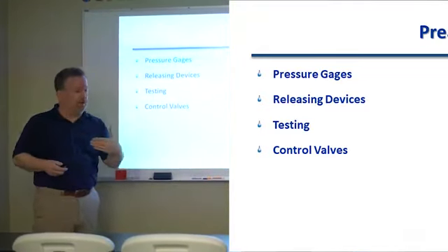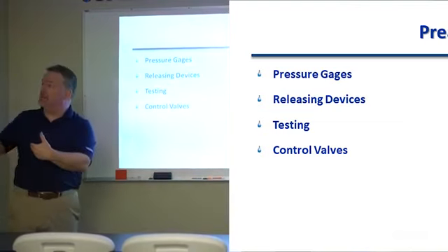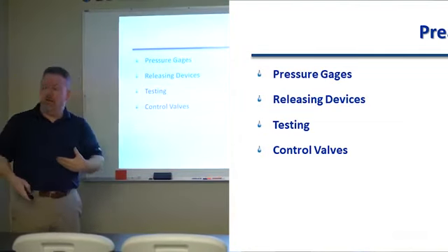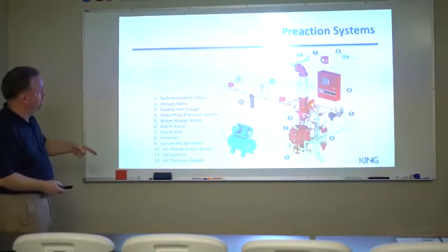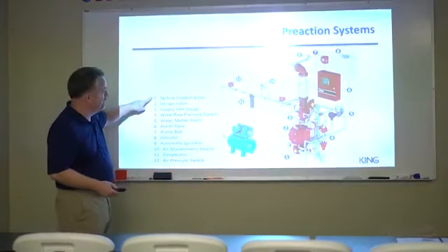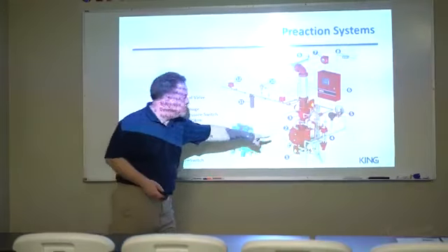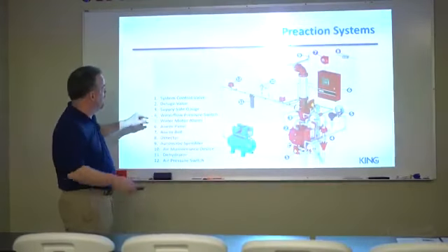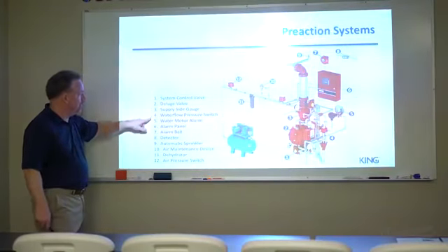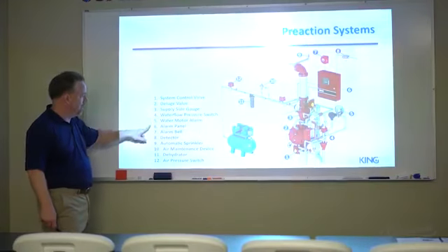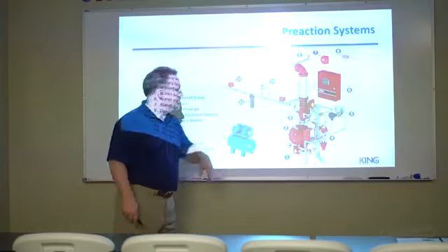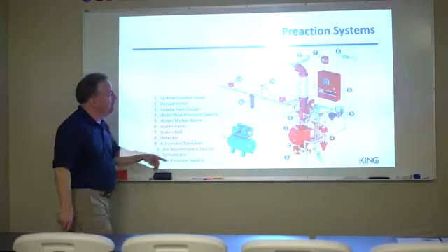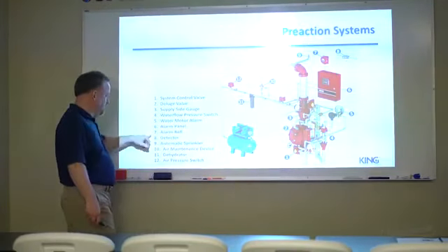And if it's what we call a double interlock pre-action system, basically what happens is the alarm devices go off. Here's our system control valve. This is actually a deluge valve right here. It's just wired a little bit differently. Water flow pressure, water alarm motor on. All of these go down through. You can see them on your diagrams as well. But primarily what we have here is number 8 is a detector.